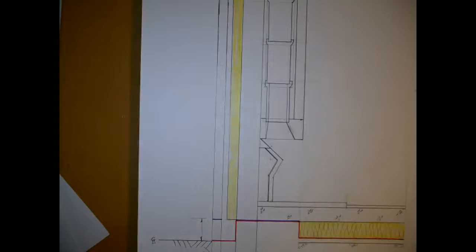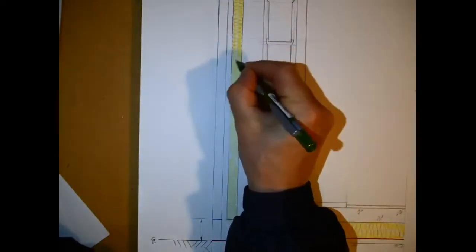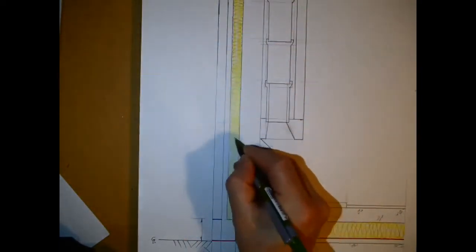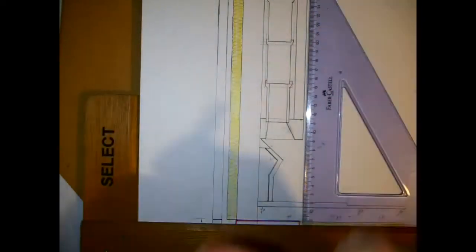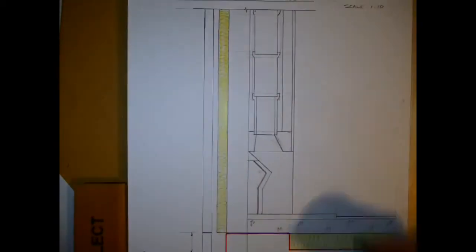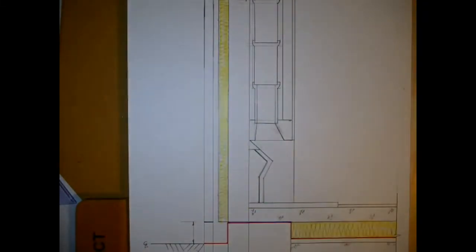The other details that we want to have in here as well, have insulation, non-combustible, naturally enough, behind where the fireplace is. Like I said earlier in the video, it's not recommended to have a fireplace on an external wall because of the risks of temperature differential, which affects the draw and the functioning of the fireplace.